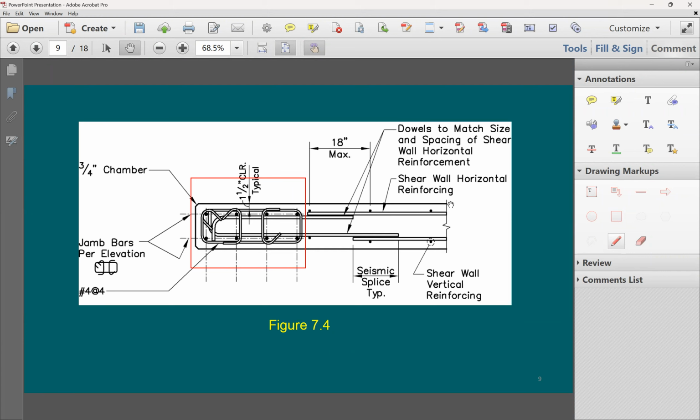I have 2 layers of rebars. So what I need to say is 2 times 0.31, correct? It's going to be all the rebars I have there. The spacing that I have between rebars is going to be 16 inch, so I need to divide by the spacing. And the wall thickness is 16 inch. And this should be the right way of doing it.